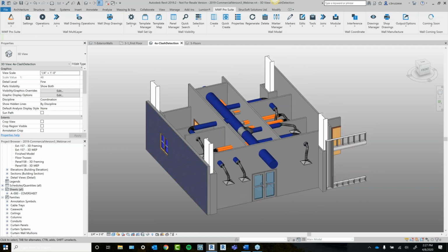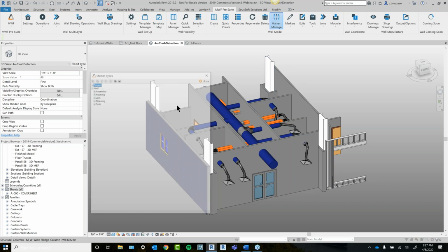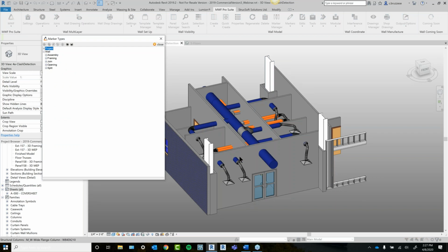Okay. So last rule set I'm going to cover maybe might be the lesser known of the 3 rule set options. But there is an option to set up rule sets when you're using the interference tool and running any kind of wall coordination. So it's a rule set, so we're back in the same spot. And you'll notice I have one here called clash detection.